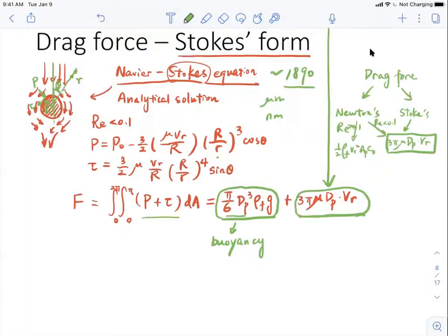If you look at this system here, the fluid is passing by the sphere, right? We assume that the gas molecules, of oxygen and nitrogen, are being dragged on the surface of the sphere. But if we further zoom in and make the particle shrink, smaller and smaller, until it has a size similar to the gas molecules, will these molecules still drag on the surface of the sphere? The sphere is already very small, and the gas molecules are not going to get in contact with the sphere at every location.